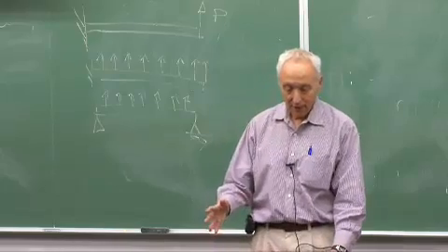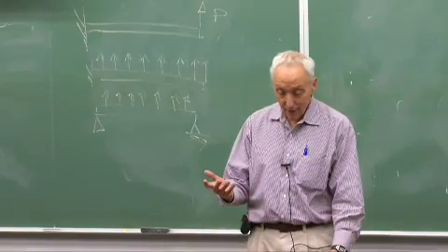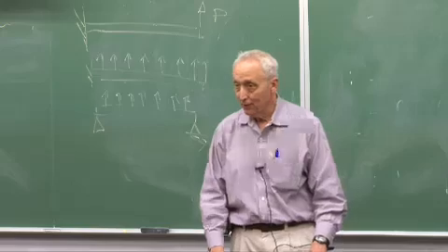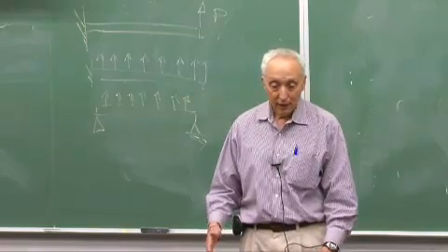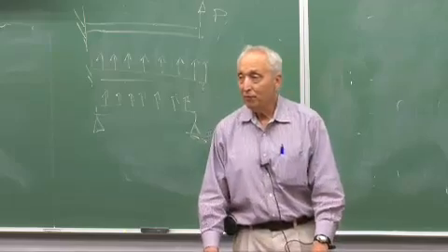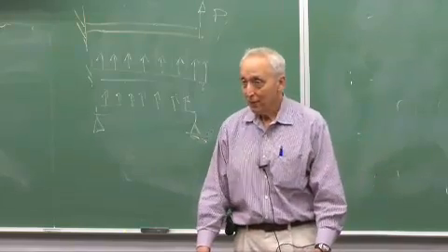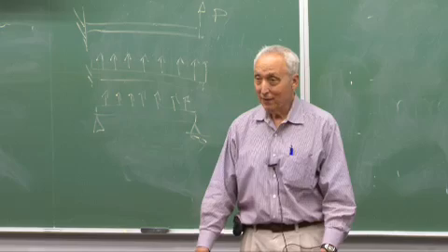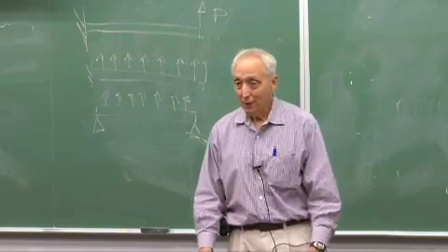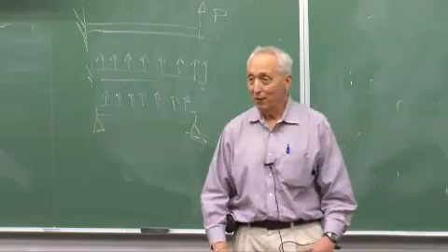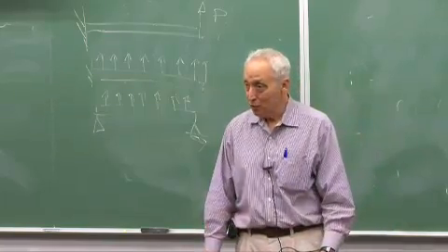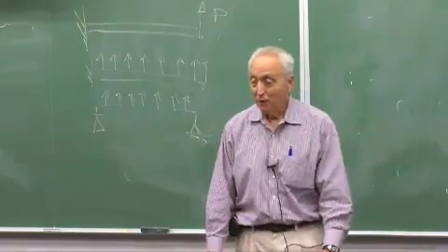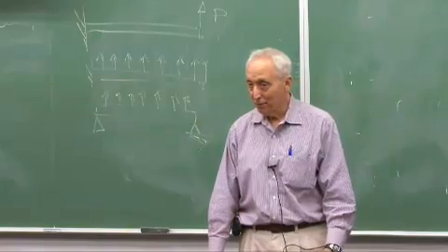So one thing that Ilan said is that if you know the order of convergence, you can extrapolate more effectively. And the other thing is a bit more basic. It's very rare that your mistakes will make the order of convergence higher than you planned on, they usually make it lower, which means that you will have to use a finer mesh to achieve the same accuracy, and that will simply cost you computer money or unhappy customers.